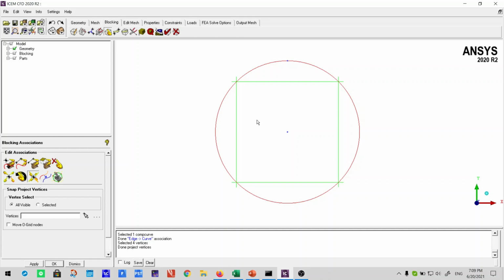to construct the structured mesh. And structured mesh means a blocked mesh, or you can say the different small blocks, or you can say quadrilaterals, or you can say the rectangular mesh. Okay, so if I've associated this, it has mapped, and I'm going to construct a rough mesh.